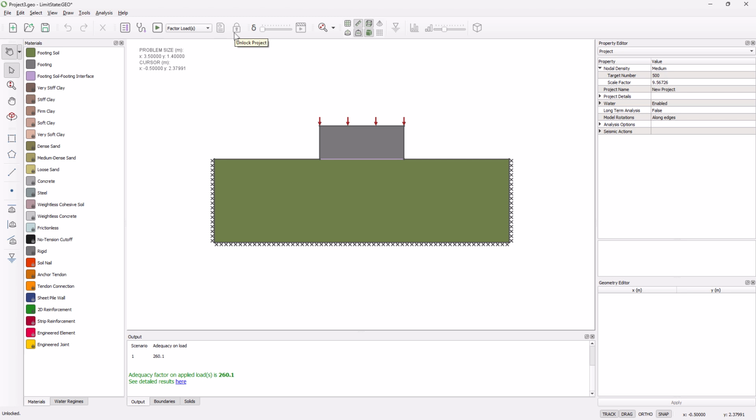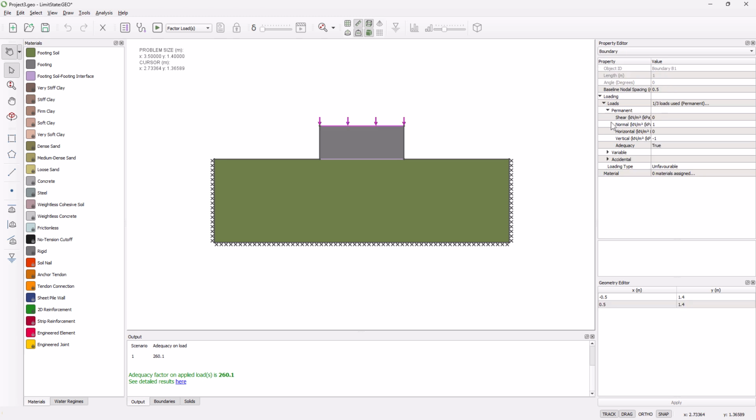And then I have one more question on triangular loads. Will we be able to specify triangular loads? In this current demonstration, the loads are basically uniform loads. It's a very good question. We will have a look at that and see if it's something we can squeeze into the next release. That would be the ability to vary loads in a triangular or trapezoidal mode across a block, to save having to break it into individual sections.